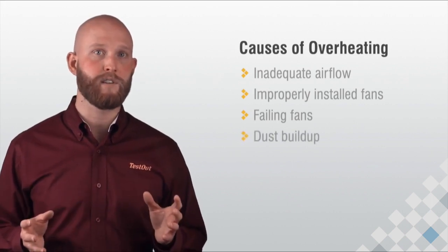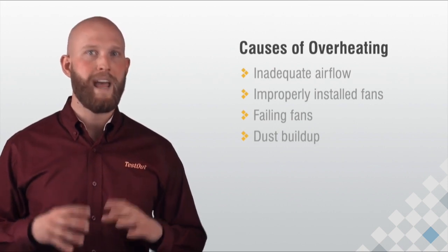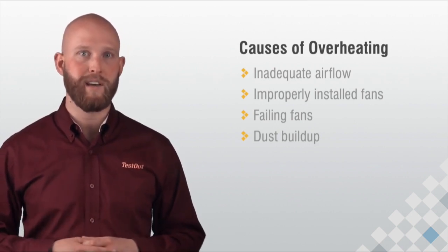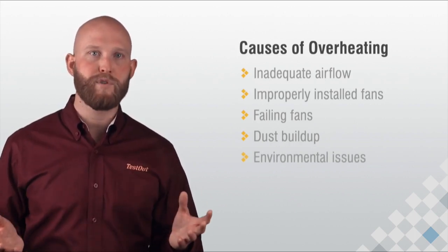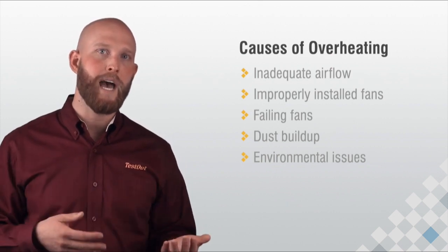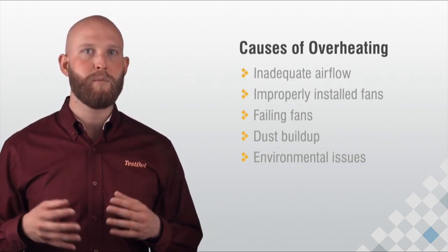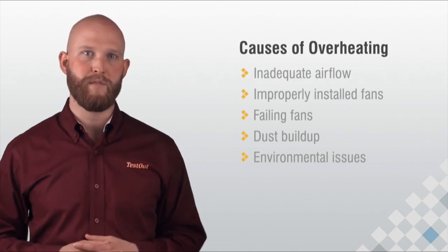Excessive dust within the system can block airflow and cause overheating. You can use compressed air or an anti-static vacuum to remove dust buildup. Environmental issues can also cause problems. If the air temperature outside the computer is already overly warm, then the temperature inside will be overly warm too. You should implement a proper HVAC system in your work area to remove excess heat from the environment.